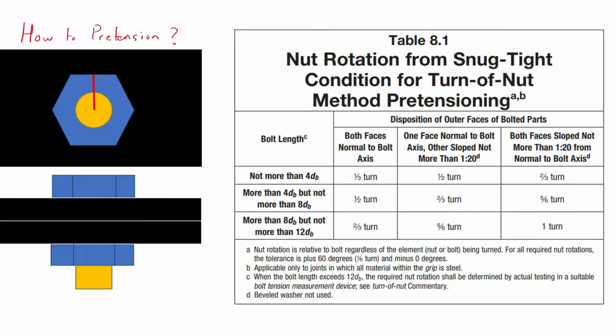One full turn of a nut corresponds to a fixed length of travel along the bolt threads, which can be correlated to the elongation of the bolt. The stress-strain relationship for the bolt material can then be used to compute the tension in the bolt. For any size and type of bolt, therefore, the number of turns of the nut required to produce a given tensile force can be computed.